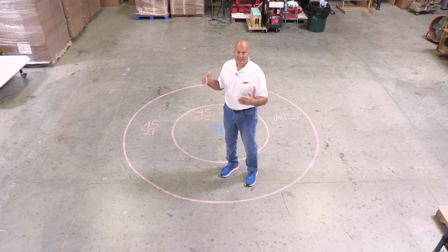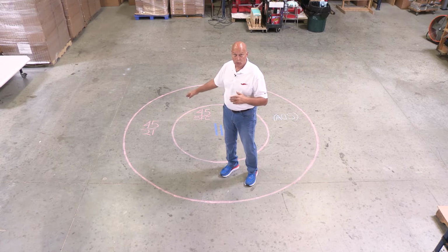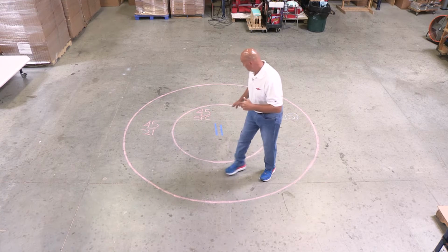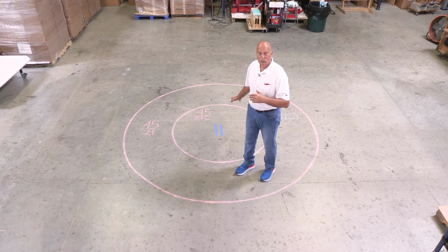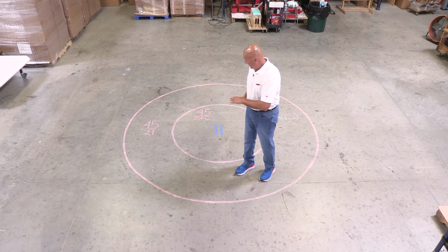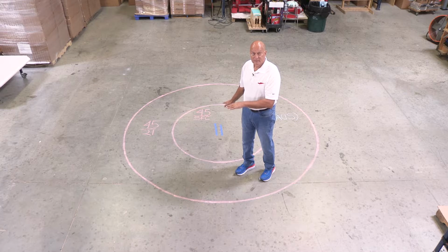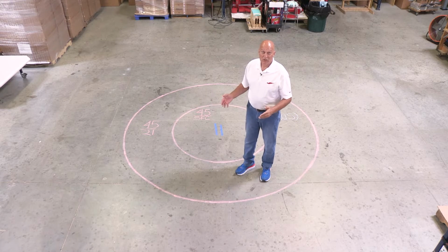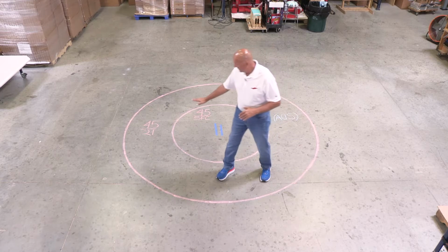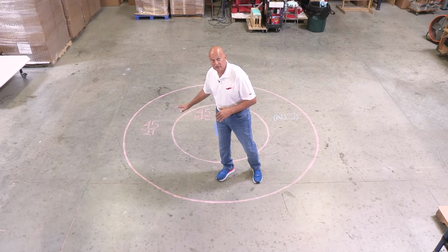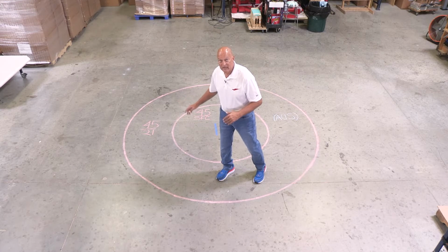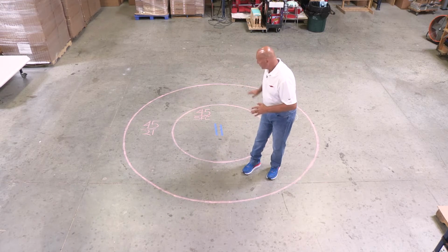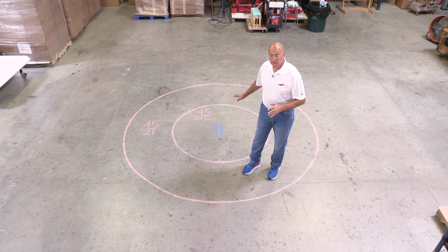So what that means is that if you're looking at 2,100 feet MSL, and the actual surface level of Austin is roughly 500 feet MSL, you're looking at about 1,600 feet to play with underneath this bottom portion of the shelf, underneath Class Charlie airspace. So this is what Class Charlie airspace can look like.